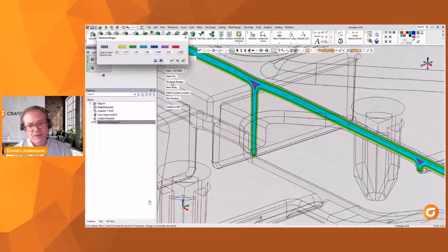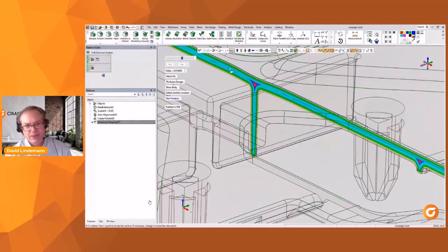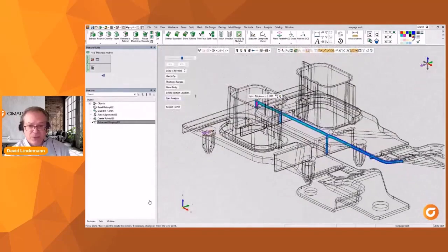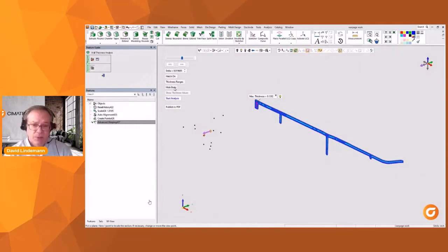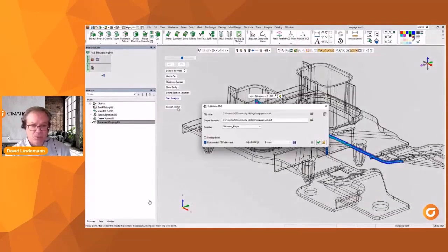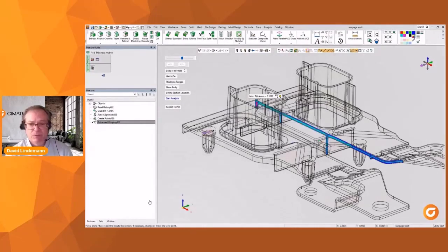All right, so I can see that the general thickness is in that light blue, and it's just barely touching on the dark blue, which means it's holding pretty consistent all the way through. Of course, where there's a wall intersection, that's thicker. Okay, that makes sense. But overall, I would say that this is telling me that I've held a consistent wall thickness.